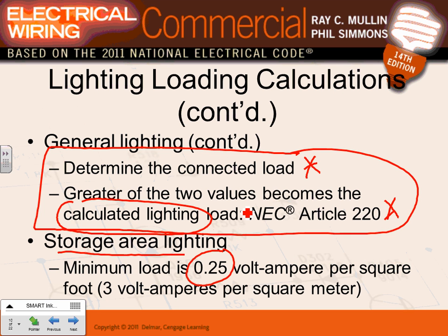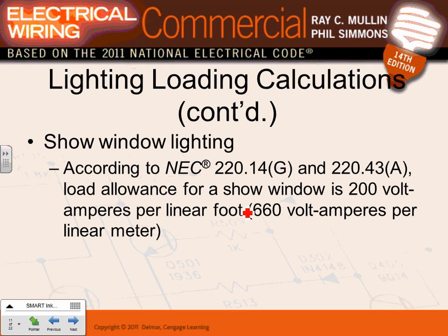Yes, you can. Typically, guys, most of us, if the building is 80% office building, the 20% is just hallways and support areas. Apply the 3 volt-amp per square foot for all of that. Can I get you guys to understand that one? Now, can you split the office building into office area and shipping area and hallways and all this good stuff? Yes. Is it worth it? No. Cool. So that's what I want you guys to understand.